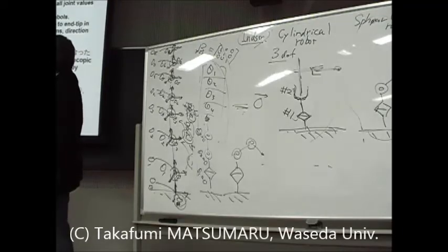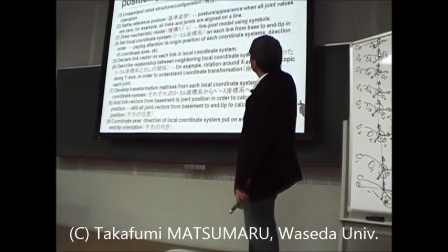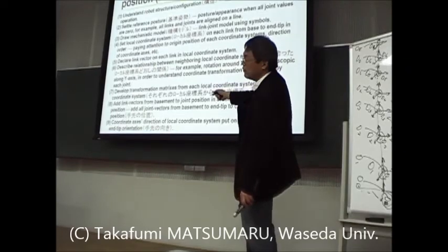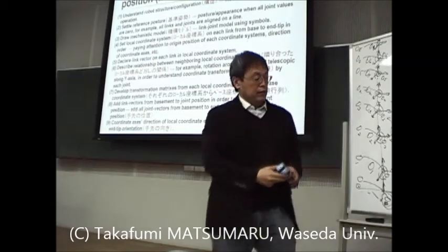And the fourth, set the local coordinate system on each link from base to end in order. Pay attention to the origin position of each coordinate system and the direction of the coordinate axis.